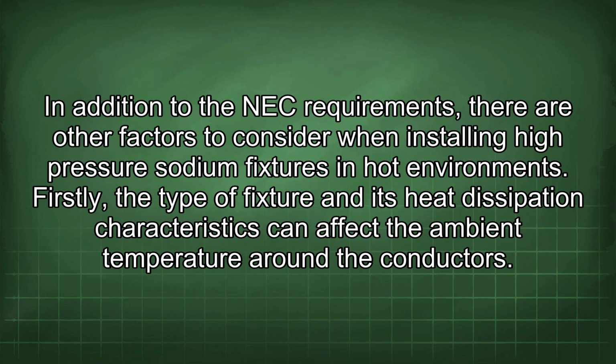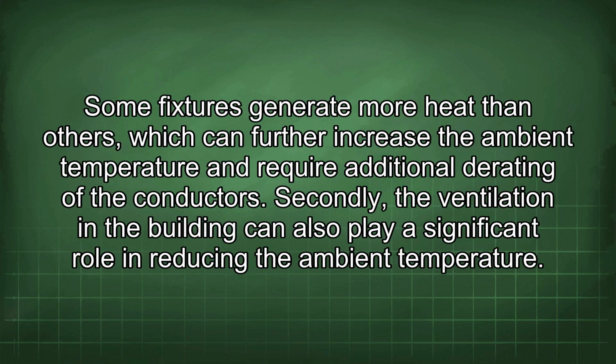In addition to the NEC requirements, there are other factors to consider when installing high-pressure sodium fixtures in hot environments. Firstly, the type of fixture and its heat dissipation characteristics can affect the ambient temperature around the conductors. Some fixtures generate more heat than others, which can further increase the ambient temperature and require additional derating of the conductors.